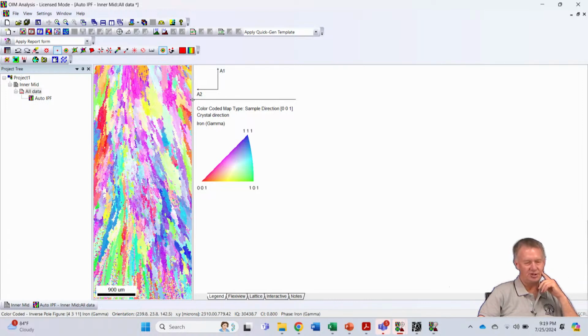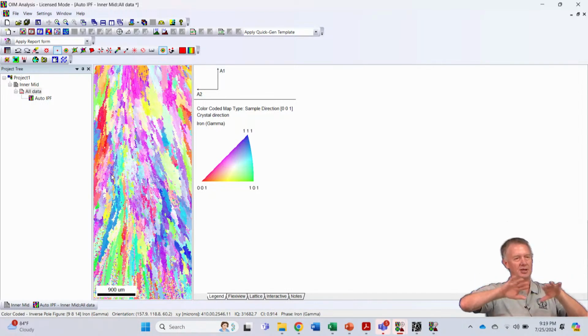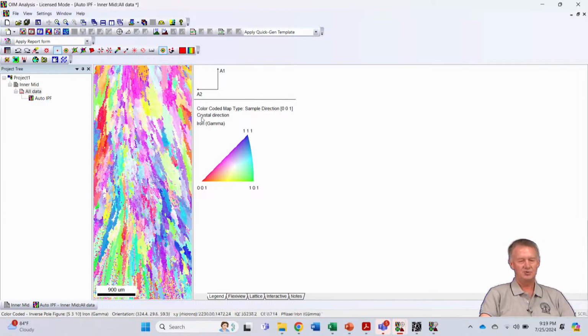So you see some regions that are starting to point over to the side, and that's because they're going on top of a solid. So typically a solidification direction, we would expect a 100 growth direction going in the highest thermal gradient direction. But in this case, it's being deposited on top of some corners. So it's coming down on top of that, and the stuff near those corners is pointing in the direction along the interface of the carbon steel. So that's what starts to happen here.